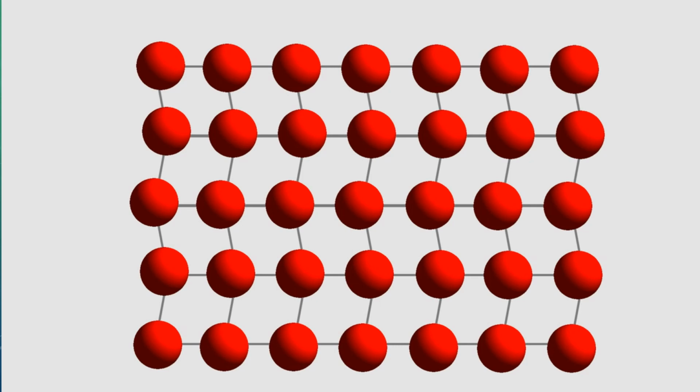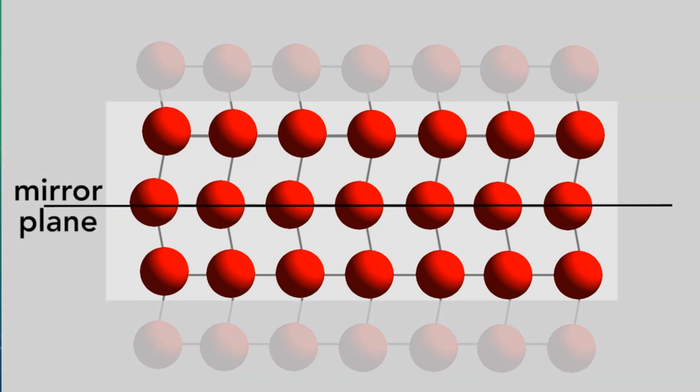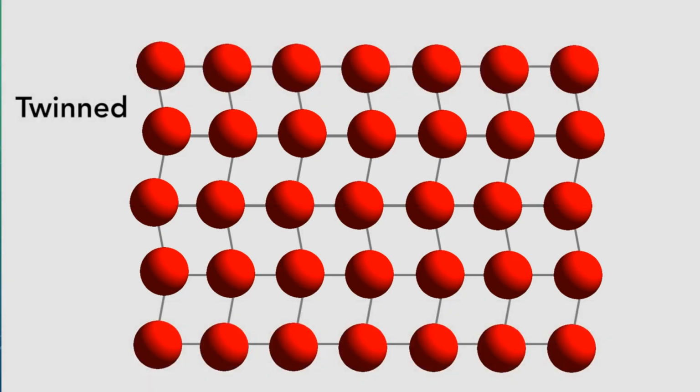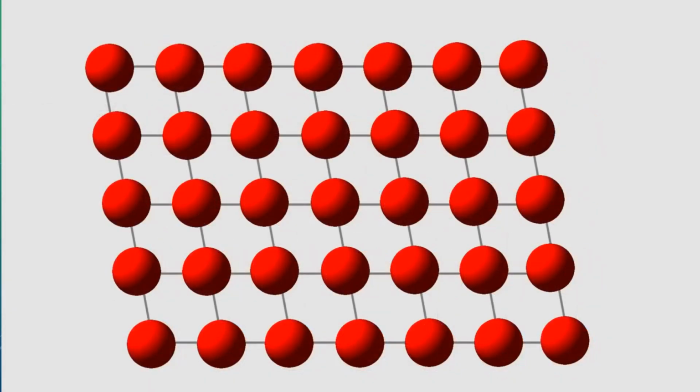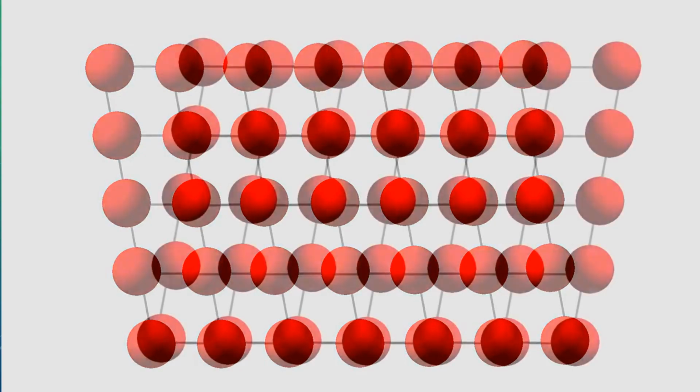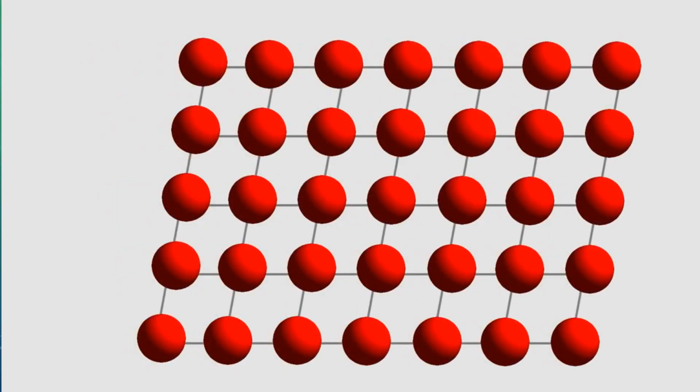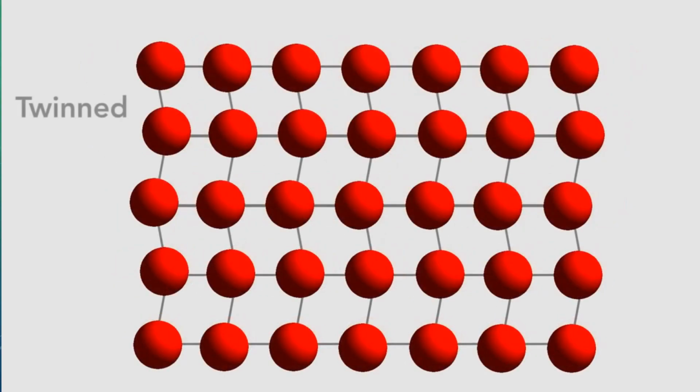It's composed of rhombuses that are mirror images. For example, notice the positions of the atoms above and below this line aren't identical, but are reflections of each other. This is called a twin structure. You could have all of the rhombuses oriented this way, or this way. And as you can now see, when the nitinol cools, it forms equal amounts of these two orientations of rhombuses.